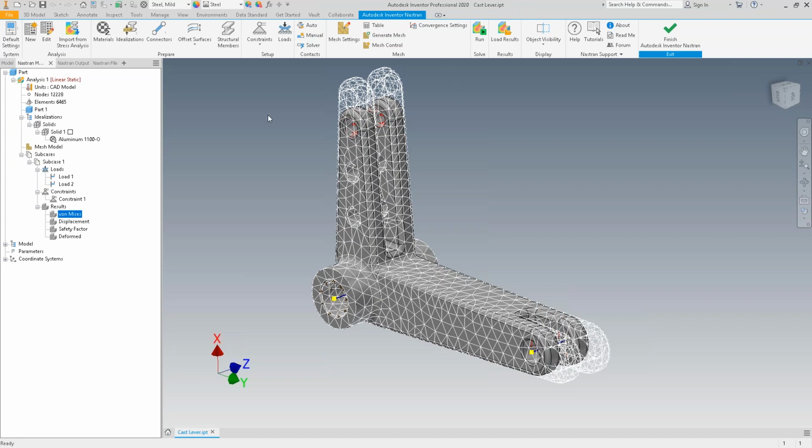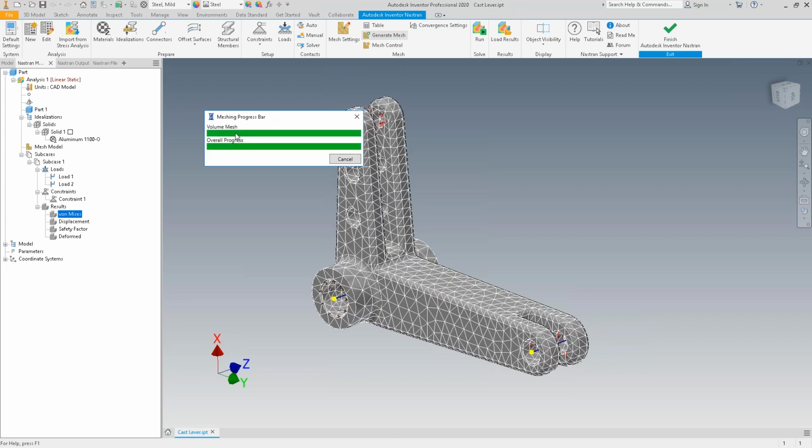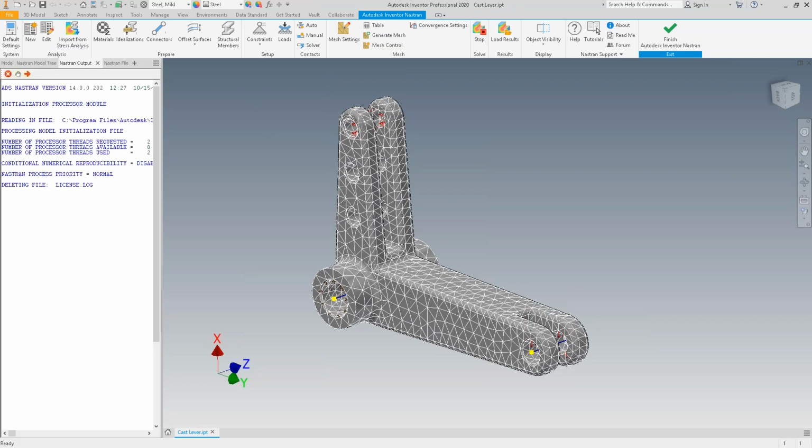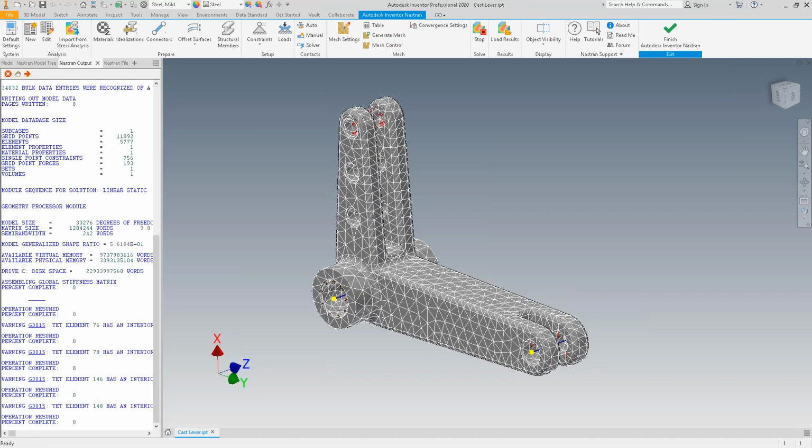Now, granted, if you make a change and it blows away a face or an edge, you probably have to reestablish something because it lost association with that face or edge. But for this particular example, everything stays. Granted, the mesh is out of date. That's an easy fix. Let's just regenerate. It regenerates based on the new geometry. And let's rerun the results. That's how fast we can get results and not like those results.